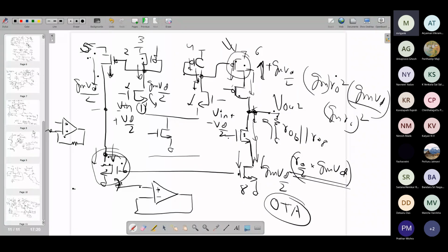So all throughout you have been dealing with this kind of operational amplifier, differential input, single-ended output. But in many cases, people prefer fully differential. That means you have the differential input as well as differential output. So this can be easily converted into fully differential also. You just have basically the other side, right? Whatever I have drawn, it will be replaced by the same cascode configuration.